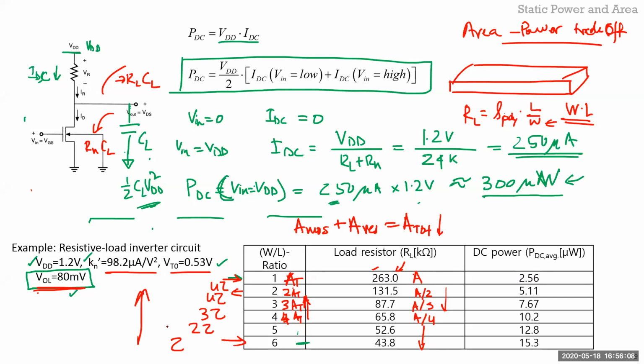There's no one single answer for it. It depends on your application, and sometimes your application is such that you're not meeting your requirement. You want the lowest power but with less area, and that's when you want to look at a different device or a different technology, different foundry house and so on. So for a given technology, these are the available options. There will be different types of sheet rho, different types of NMOSs, different types of PMOSs. With that, and given your application constraints, you just have to design your circuit.